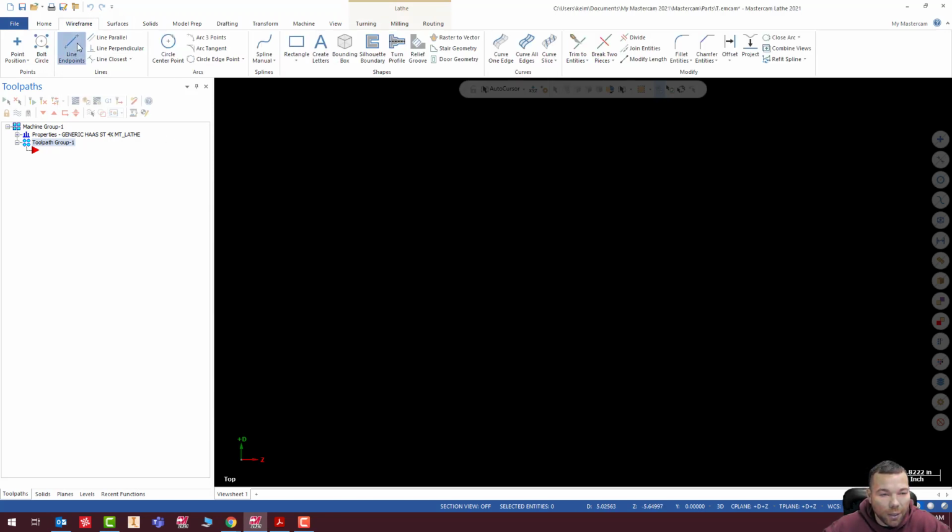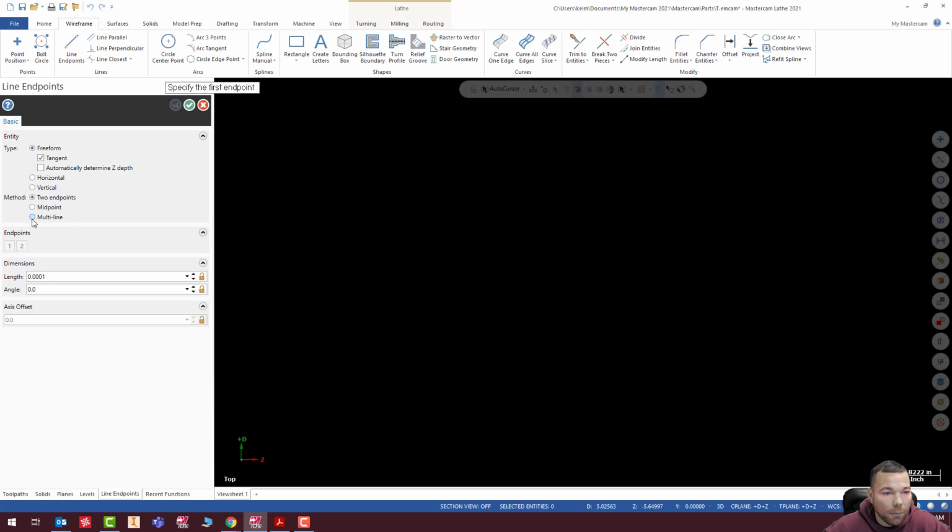So I'm just going to go to my line endpoints and do a multi-line. My strategy differs a little bit from what they show you in the book. I find this easier, so I'm just going to show you this way. First place I'm going to start is 0, 0, enter, create my line. Next one is going to be at 1.0, 0, enter.